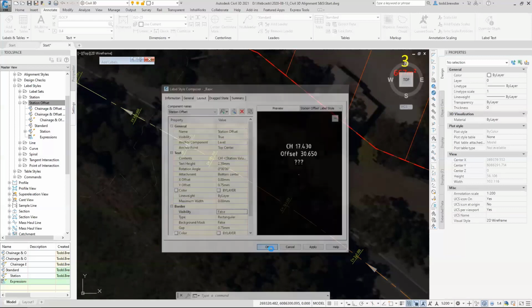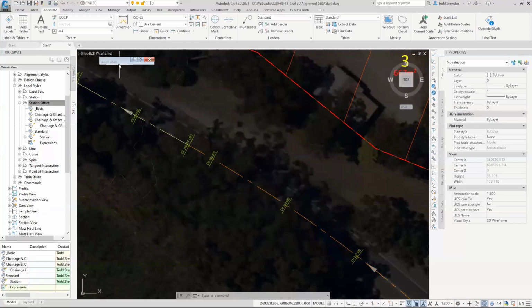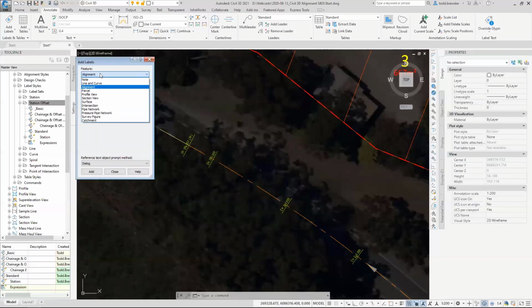All right. So let's go and apply this. So let's go alignment. We want station offset. There's 2 station offset types. So this is functionality wise, fixed point and just station offset. Station offset, you nominate the station or the chainage and the offset. Fixed point, you nominate the point and you calculate. So one stays fixed, one moves with the alignment. So let's do a fixed point one.